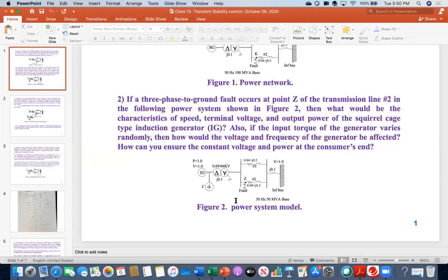So what you need? You need to use the energy storage device. You need some compensator. At the grid point, you need to connect the energy storage that will compensate those fluctuations, because energy storage can work both in charge mode and discharge mode. So by consuming power, by sending power, it will minimize and it will provide your required power. So therefore consumers will not be affected.